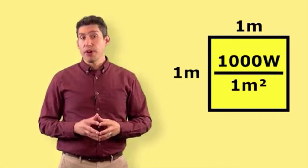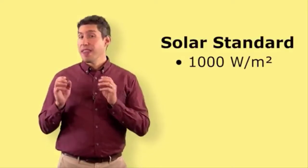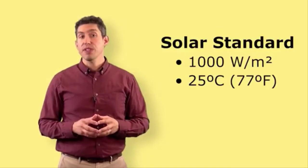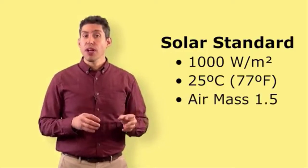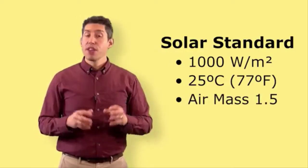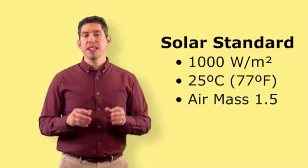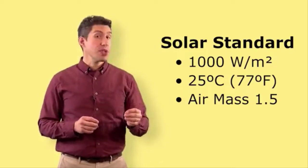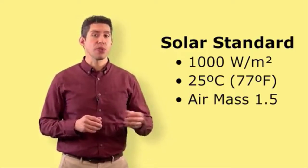It's an easy number to remember and use, and it's pretty close to the actual terrestrial brightness, so we define this value as the solar standard. We combine that brightness with a standard temperature of 25 degrees Celsius, which is around 77 degrees Fahrenheit, and another term called air mass, to give a definition that combines solar and climatic conditions. The chosen air mass value is 1.5. We will discuss the definition of air mass in a following lesson, but suffice to say these three pieces, the brightness, the temperature, and the air mass, are what are going into determining the efficiency of our photovoltaic modules.